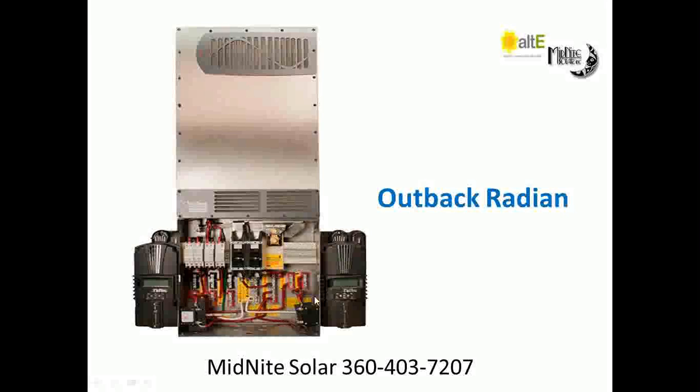The Radian E-panel is available in multiple flavors. If you wanted just the E-panel not pre-wired, we have a single Radian E-panel, we have one prepped for a single Classic, and one prepped for a dual Classic, and then we have a master Radian E-panel that will do 2 Radians. That's something that Outback doesn't even do. So we can pre-wire 2 Radians with the official bypass in one E-panel, and then of course we have the slave E-panel for the second Radian that wouldn't need any AC breakers.